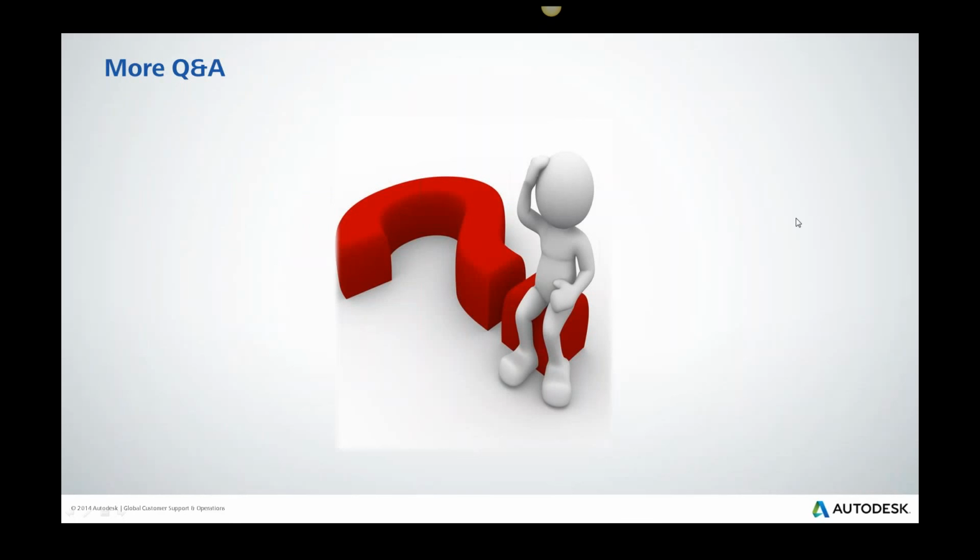Oops, sorry, I was muted. First, there was a clarification to one thing that Victoria mentioned about extrude only working on closed objects or closed 2D geometry. Somebody pointed out that if you use extrude on an open polyline, it'll just create a surface as opposed to a solid.